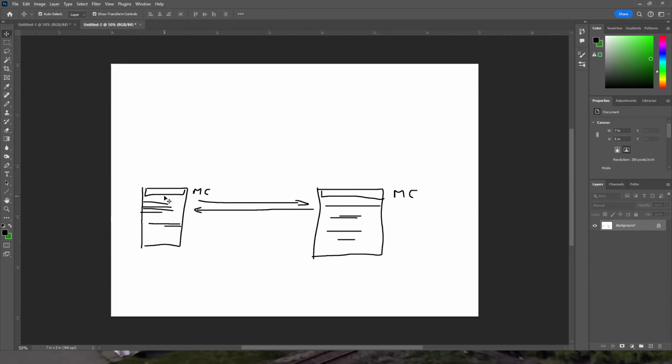And if there's any data going this way, then this media converter will have to convert the electrical signals into light, and this will have to translate it back. So one fiber optic link will have a transmit and receive line going on. So it'll be two strands of fiber optic. If you want to have more data throughput, then you consider another pair.